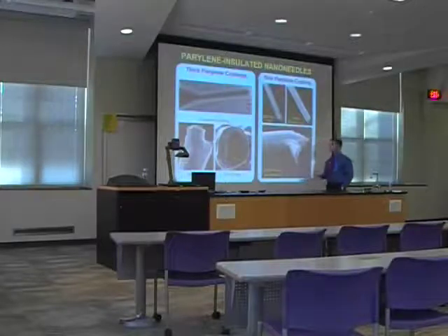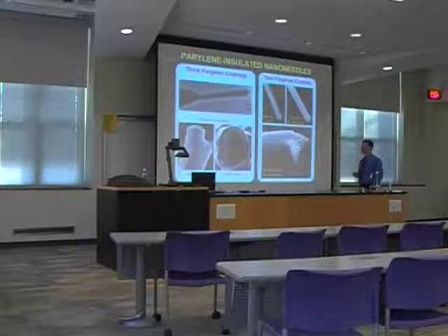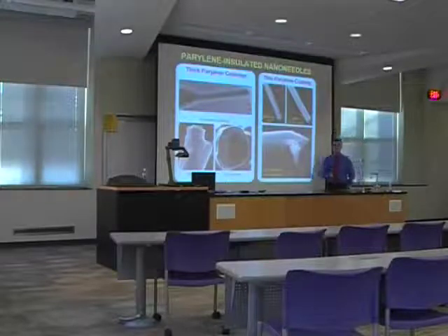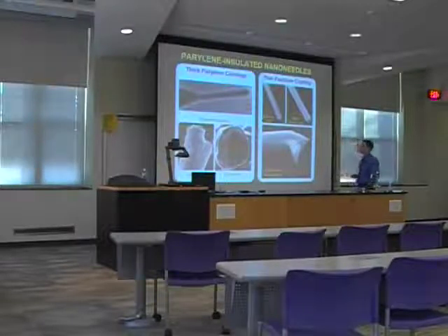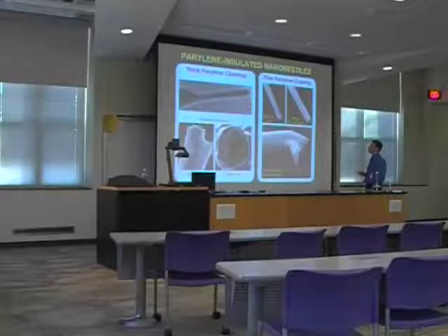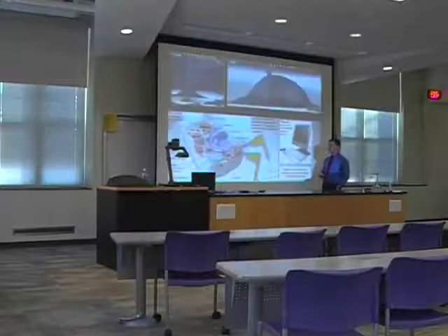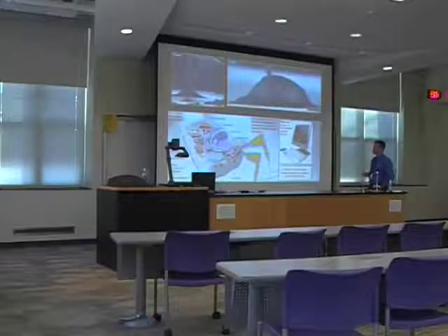Nanoneedles. Well, since they're metallic, you can coat them with a layer of polymer, cut the end, and you will obtain some kind of nanoscale analog of electrical cable. So we have an insulating layer and conducting core. After that, this kind of nanoscale electrical cables can be used for electrochemical measurements inside the living cells.